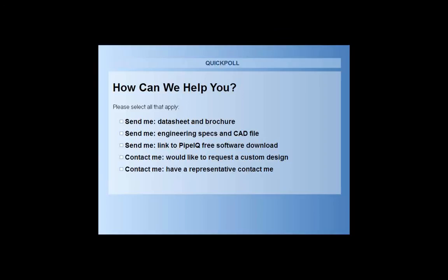talking about pipes here. What type of piping is recommended for PipeIQ or for FAAST? The standard pipe that we use is a CPVC pipe with a BlazeMaster resin. But any pipe material, as long as it meets the internal and external diameter requirements, is acceptable as long as it's approved by your AHJ. So if you want to use copper, PVC, PE, that's okay. Again, FAAST only really considers the internal and external diameter of the pipe.